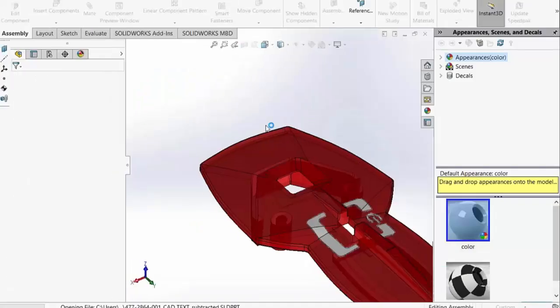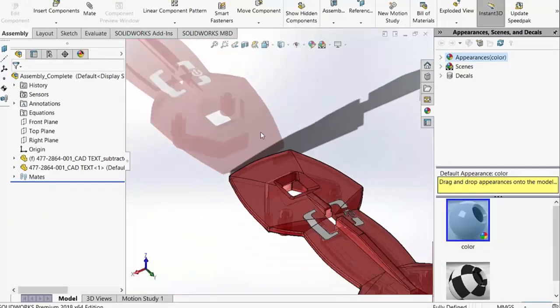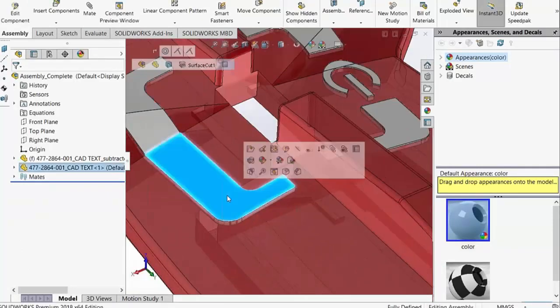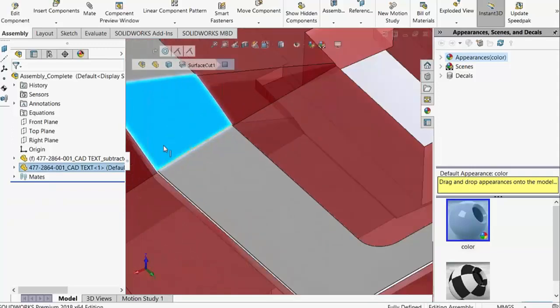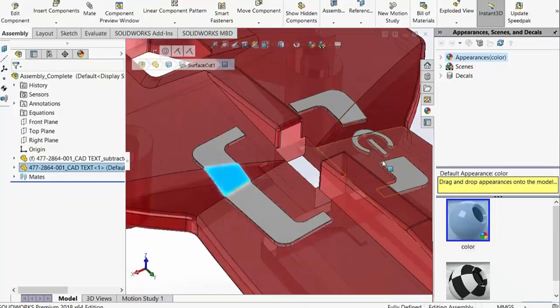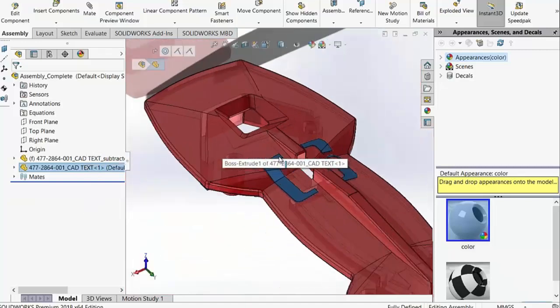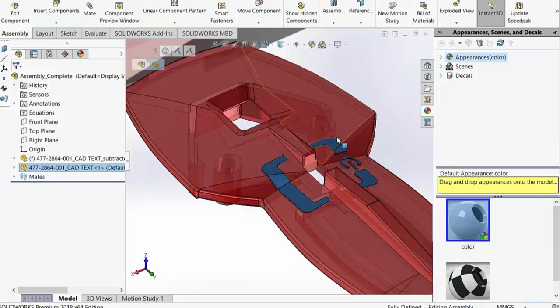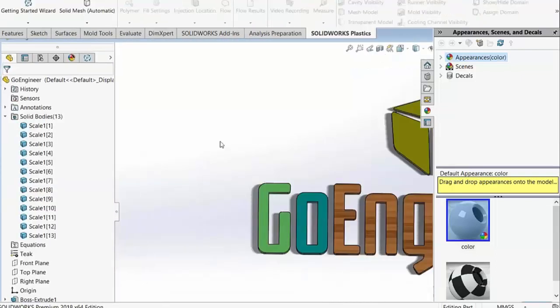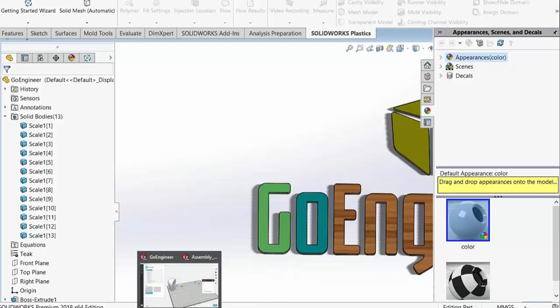Essentially the first step in that would be to create that feature as a portion of an assembly within SolidWorks. So here we see what I did is I essentially took an image sketch, created it essentially as a feature, cut it into the model, did some Boolean subtraction features, and now I have an assembly where that pad printing element is represented as its own body. From there, I think you can draw the quick connection as to how easy this would be.